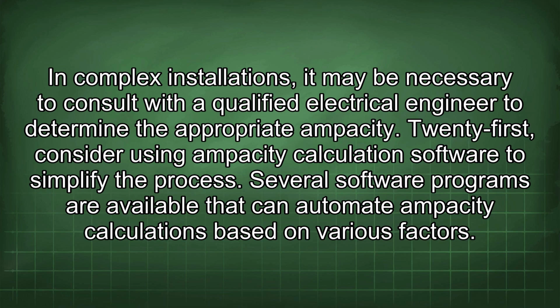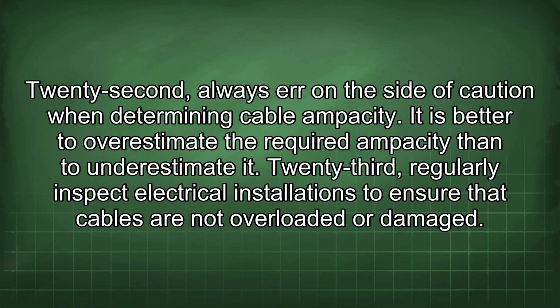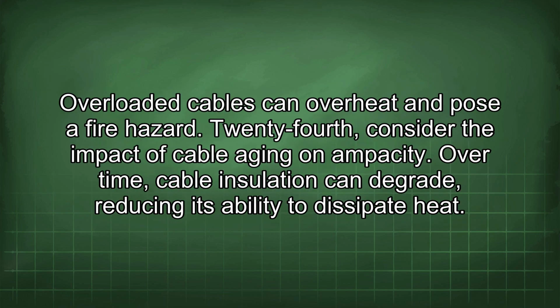21st, consider using ampacity calculation software to simplify the process. Several software programs are available that can automate ampacity calculations based on various factors. 22nd, always err on the side of caution when determining cable ampacity. It is better to overestimate the required ampacity than to underestimate it. 23rd, regularly inspect electrical installations to ensure that cables are not overloaded or damaged. Overloaded cables can overheat and pose a fire hazard.